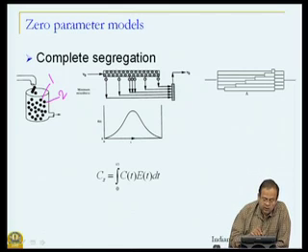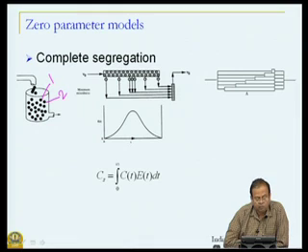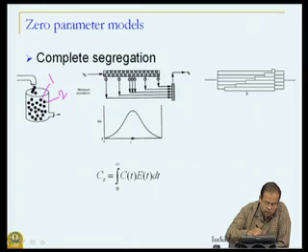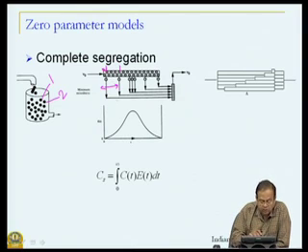The other way of looking at that is, if you have a plug flow reactor, then the fluid elements do not interact with each other, which is equivalent to saying that having put in some material, some fluid elements come out at this particular point. So, it will have an age corresponding to this particular residence time, whatever that is. For this, it will have a residence time fraction of this. So, it comes out a little later in the reactor and so on.